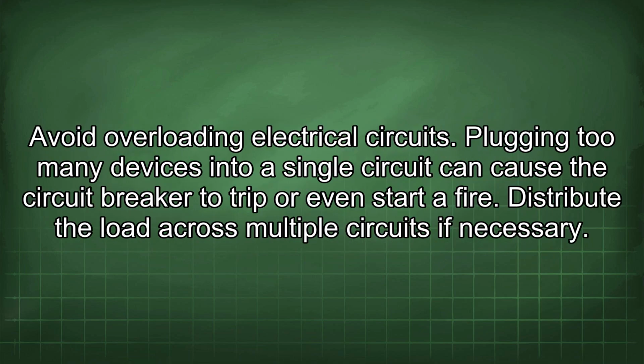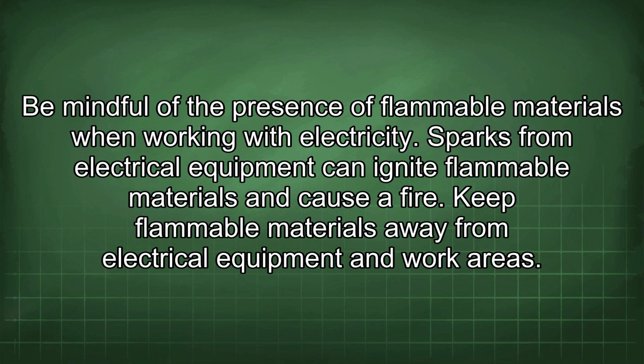Avoid overloading electrical circuits. Plugging too many devices into a single circuit can cause the circuit breaker to trip or even start a fire. Distribute the load across multiple circuits if necessary. Be mindful of the presence of flammable materials when working with electricity. Sparks from electrical equipment can ignite flammable materials and cause a fire. Keep flammable materials away from electrical equipment and work areas.